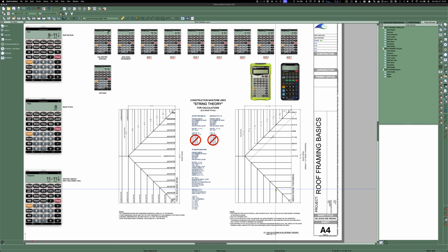So this is better. There's your outside wall, and you're bumping into the ridge. And that is your span minus this ridge thickness divided by 2. So that was 9'11 1/4. And what I would do is I would take that number and I would do the math.